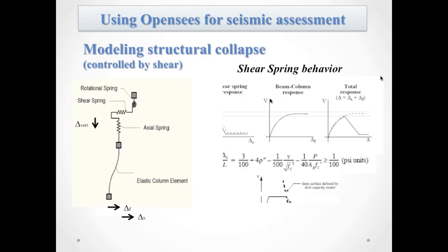The limit state uniaxial material is a complex material. What this material does is track the displacement and the interstory drift of the column member, and there is a predefined relationship that relates the force with the drift, and this is practically a surface. When the force lies inside the surface, then shear failure is not initiated.